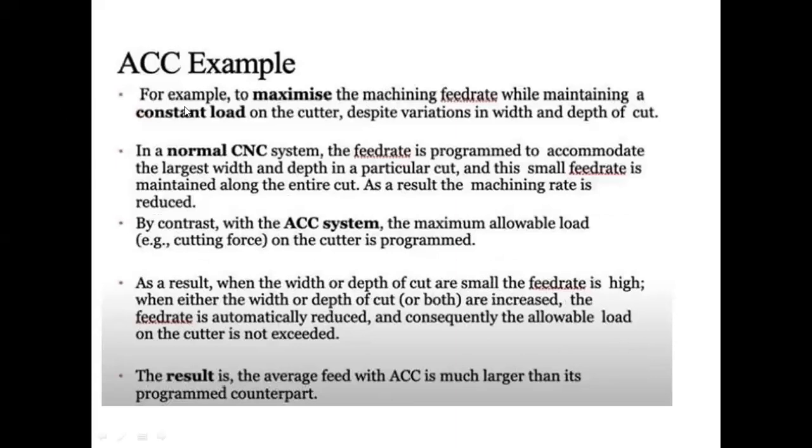Okay, now we'll see an example. To maximize the machining feed rate while maintaining a constant load on the cutter. For example, this is what we are trying to do: I want to have a maximum feed rate while considering the fact that there should be a constant load on the cutter. The cutter should not have varying loads, it should only have a constant load, for example, maybe 1000 newtons. Based on this 1000 newtons, at different points of time you will see whether the load maintained is 1000 or not. If it is not 1000, you will make it 1000. How? You'll change the depth of cut, for example.